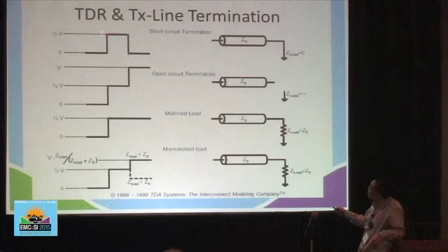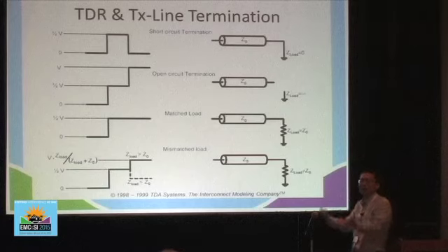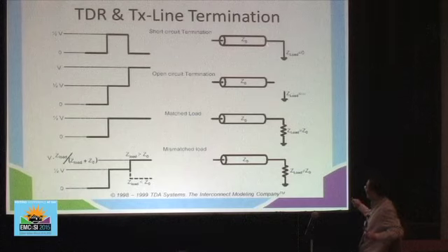Now in this case, if at a certain time the voltage from half of the source voltage jumps back to 0, that tells us your load is a short, because the short has a -1 reflection coefficient. When it comes back and you add them together, they cancel and it becomes 0. So if we see at this junction the total voltage comes back to 0, then we know this is a transmission line terminated with a short circuit.